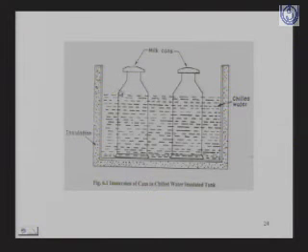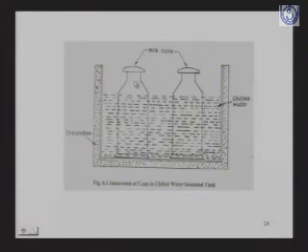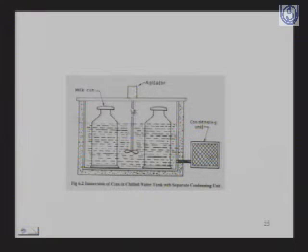It can be of capacity 2, 4, 6 or 8 cans depending upon the capacity of the collection center, and then you can chill the milk cans in this. So you take the chilled water, put it into this, we put the milk cans, the level of chilled water should be at minimum up to the milk cans level, and this is how we chill them. The next is an additional thing, that this is with refrigeration.